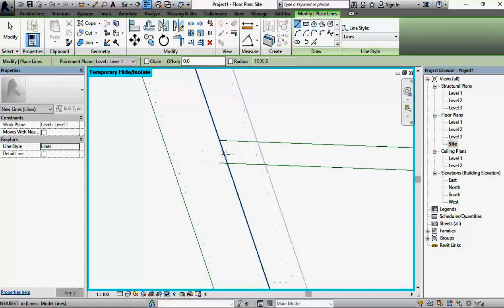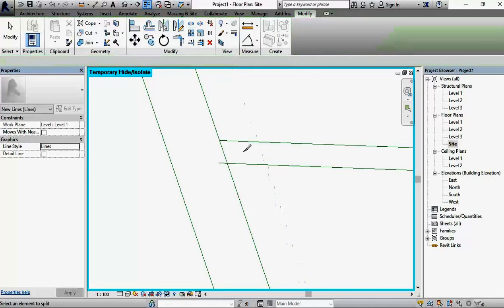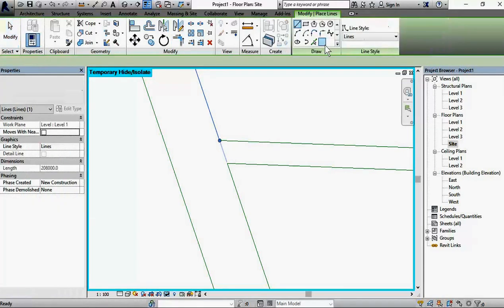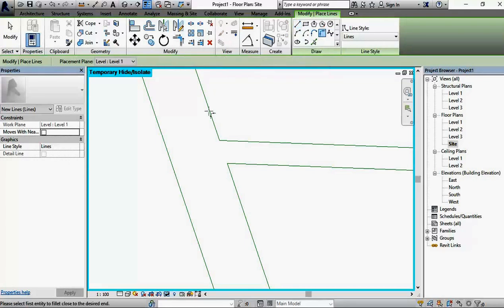What I want to do is I want to split this here. So in the modify tool, this item, that's split element, select it, split it right here. What this does is creates two separate lines. So when I have to trim and extend this corner, okay, that's this tool here. Select this, then this, select this, and what we could do, select this, create similar,